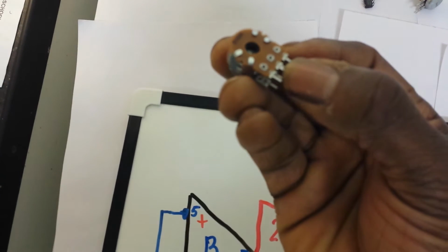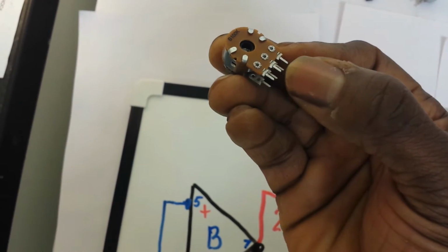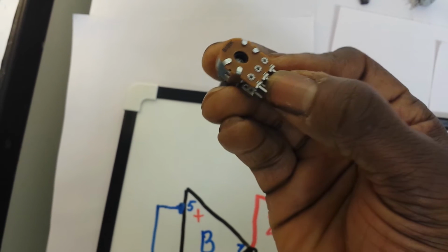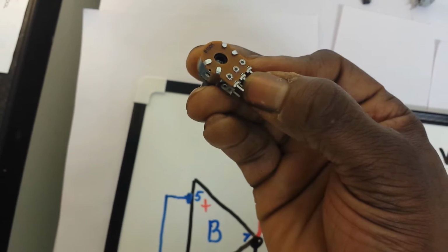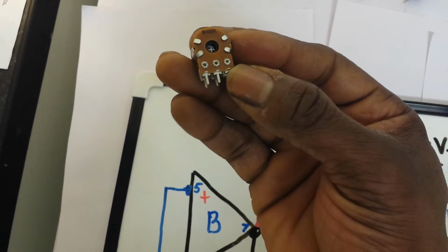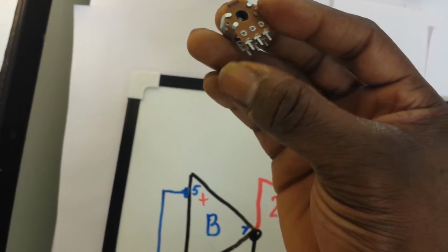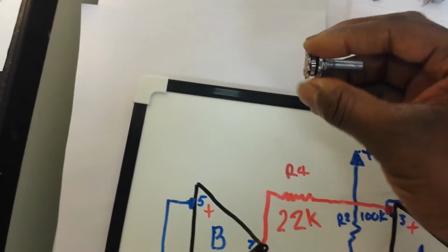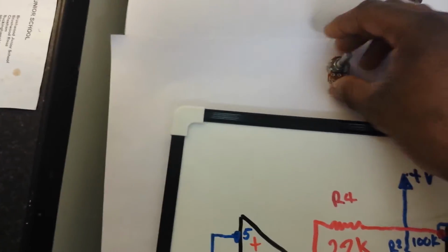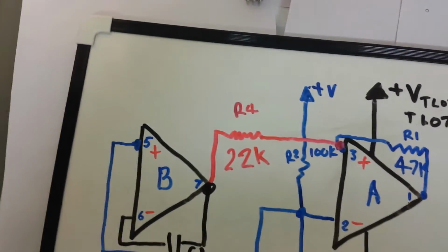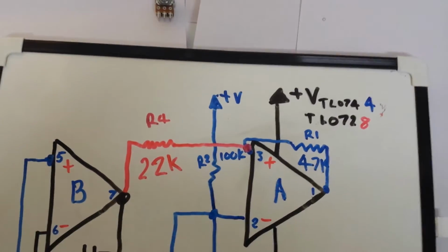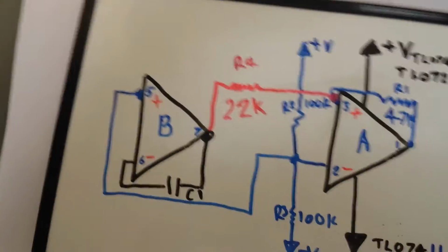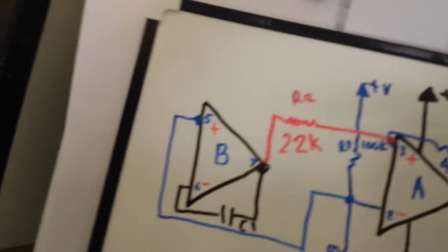Say we have the middle pin as the input, we can take the middle pin to pin 6 and take one of these sides to pin 1, and we'll tie the other one to ground. And the reason why we're going to tie the other side to ground is so that when we turn the LFO towards ground, the LFO will stop. Otherwise we will get a continuous control voltage bump from that LFO because it hasn't actually quite stopped itself.